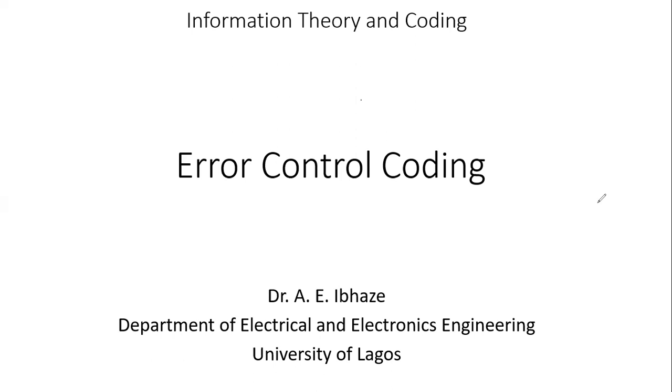Now, for us to get the code words, which are encoded or transmitted, the encoder output, we need a generator matrix, right? Remember. And if we have that in the encoder, then in the receiver we should have something to decode it. So there we are going to have a parity check matrix.